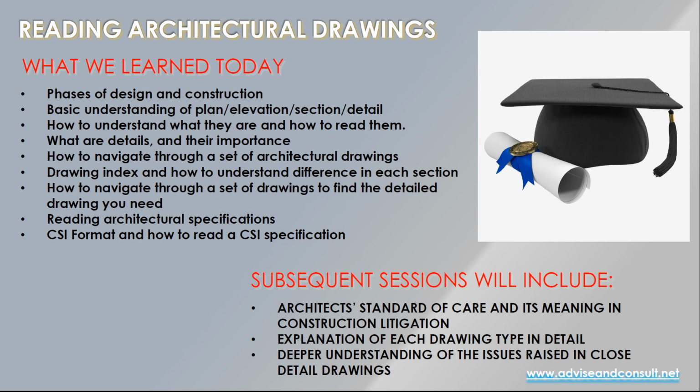But what I wanted to try and convey was so that you can understand the phases of design and construction, a basic understanding of what a plan, elevation, section, and a detail is, how to understand what they are and how to read them, what are details and their importance because that is so critical, then how to navigate through a set of architectural drawings from one end of the drawing set to the other, drawing index and how to understand differences in the sections, how to navigate through a set of drawings to find the detailed drawing that you need, reading the specifications, the CSI format.